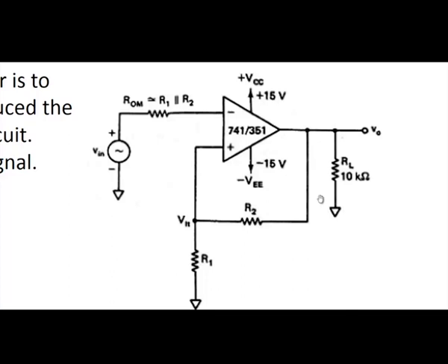Here some of the output voltage is fed back to the positive input terminal of the operational amplifier through two potential dividers, R2 and R1. So, this is now the V reference voltage, and it is some of the output fed back to the input of the operational amplifier. Why it is called positive feedback: the output is given to the positive terminal of the op-amp.